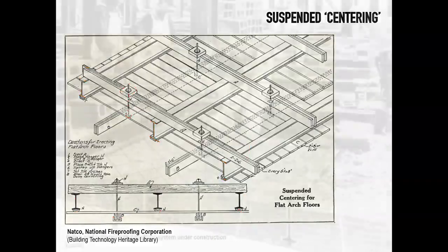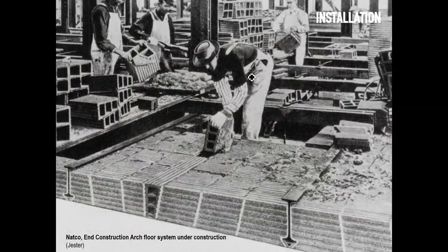It's really a decking system that allows workers to work in between the beams, walk safely on them. So you can see here the beams, and you can see here in the background some of these timber beams that have been put to run temporarily over the steel beams. This is a steel beam here, and this is some of the structure that is used to support temporarily this platform that can also be reused.